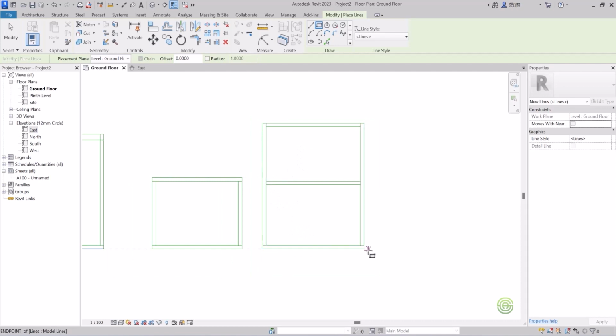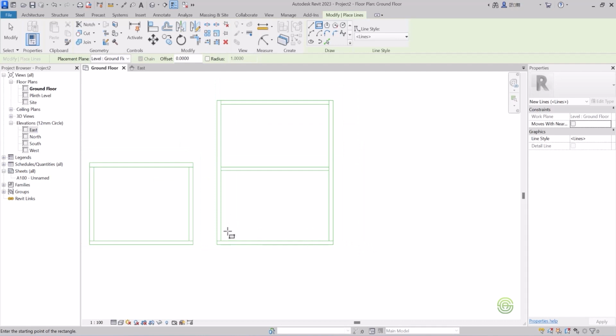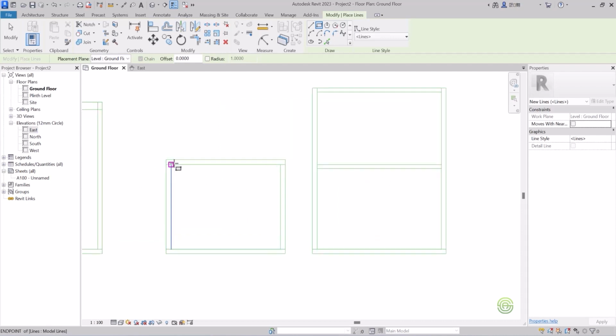The floor will be like this, the ground floor will be like this, and then you will start a wall which will continue till the first floor top. And if you want to provide a roof slab and first floor slab, you can provide that between these walls so that in elevation, a wall will be up here and there will be no overlapping or glitch kind of thing. Your floor slab will be in between the walls.